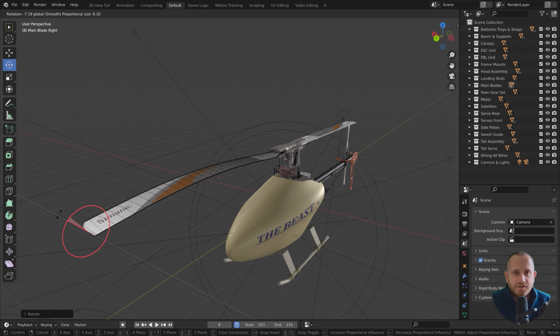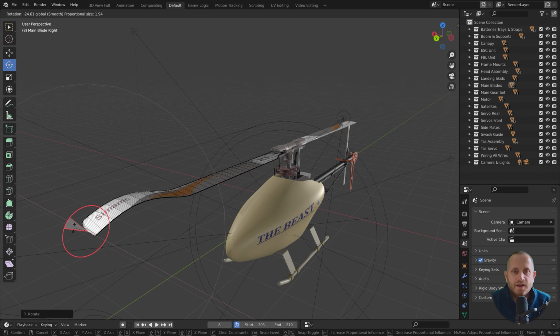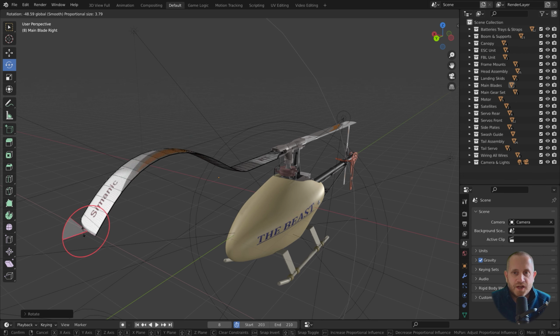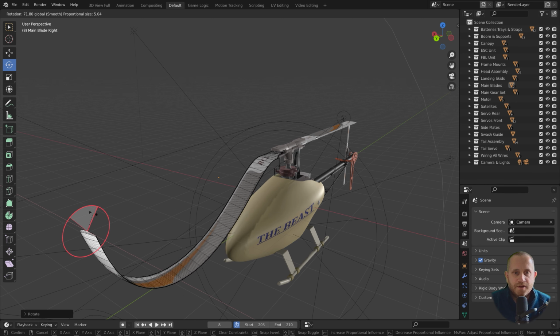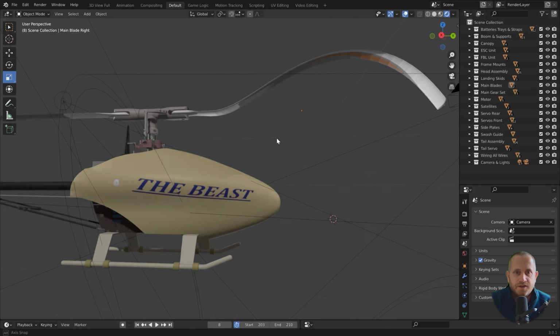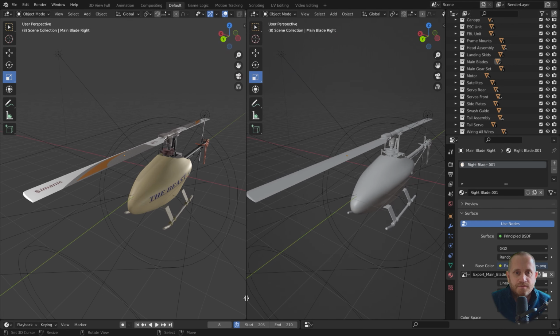By selecting Blender's proportional editing tool and using it to manipulate the vertex positions, it's possible to replicate in a similar manner what the simulator's vertex shader is doing during each invocation. Notice that the blade along its length is divided up into lots of small sections by the horizontal edges across the width of the blade, which allow the blade to bend and be distorted.